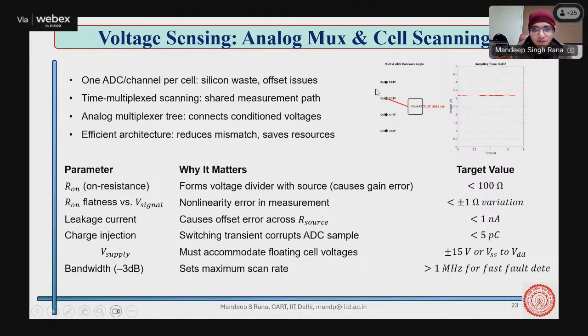Again, the same thing I told you is true for many ICs: we want to read the signal, we don't want to take current out of it. And the second thing is it should have really good switching transients. You can see that I am moving between various signals. When I move between signals, it should not have noise or overdamped or underdamped behavior. It should have quick and very good damping, say critically damped. As well as there should be a fast sampling time from the ADC.